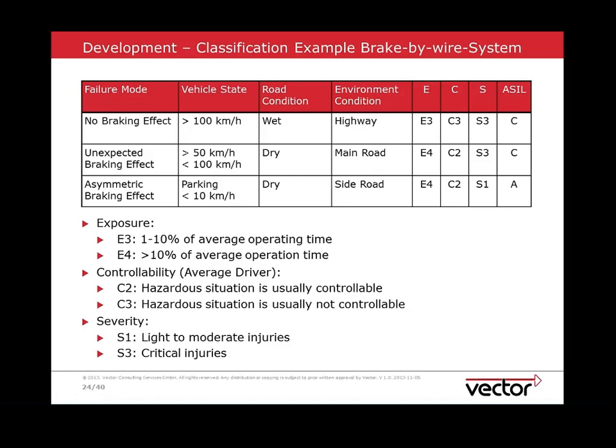I mean, it will definitely lead towards an accident. The accident itself is rather low profile because you're on a small street with low speed. So this relates to a very small level of severity, because there will not really be much of an accident, which translates finally into an ASIL A, which has a much smaller amount of safety requirements.